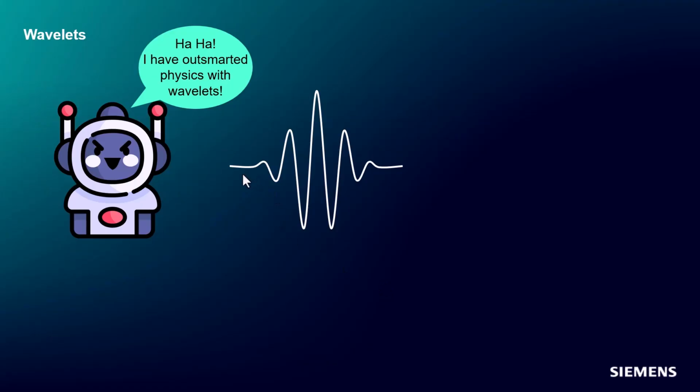So a wavelet has a pretty unique shape. It's different than just a singular frequency. It also has some type of amplitude modulation. So we have multiple frequency components of this wave. Now, instead of probing with just the single frequency sine wave, we're going to use this shape to probe our transient signal. And this shape is very unique. It does some pretty cool things for us. It allows us to analyze both time and frequency. Now, there's always a trade-off, but it is something that gives us a little more insight into our signal and it will be more descriptive, especially for these quick dying events.